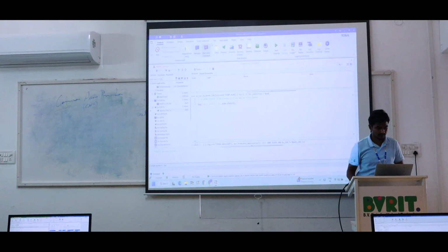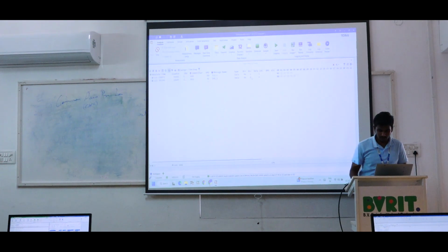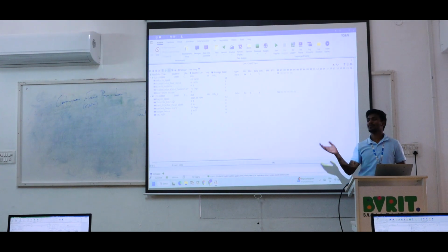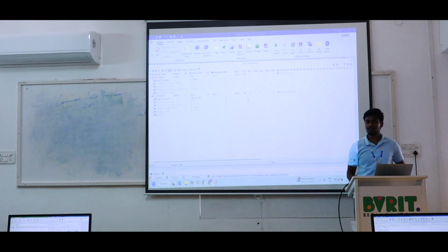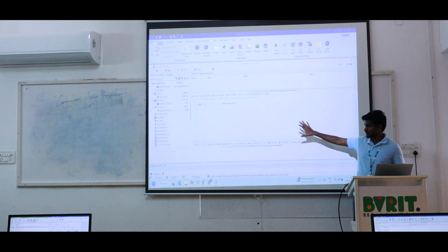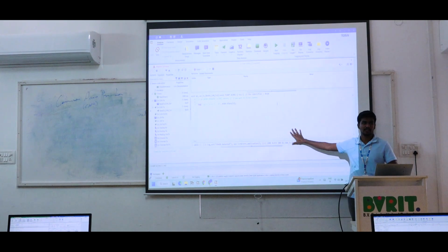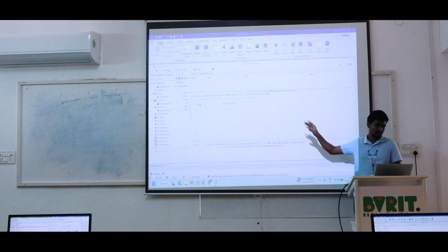Go to this trace here. It is showing the direction of the messages. I am checking the transmit only, coding and writing. Okay, so now it is showing the RX messages. The messages we have transmitted from this window itself, which means where we have the CAPL scripting, on this window it is showing the TX message. That is the message we are able to see here.